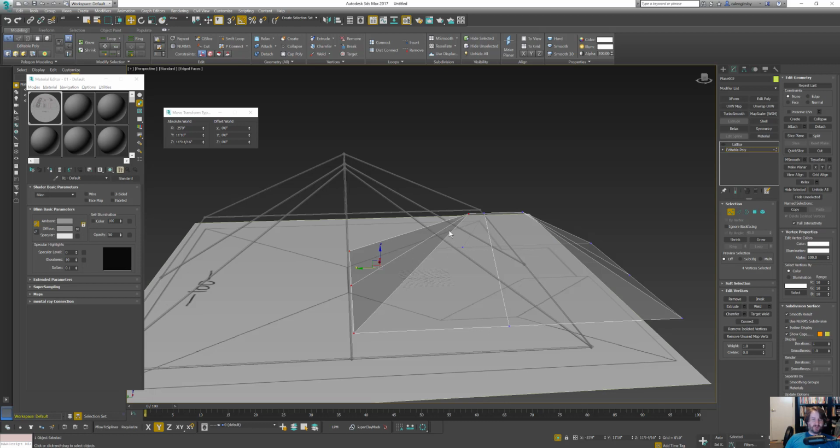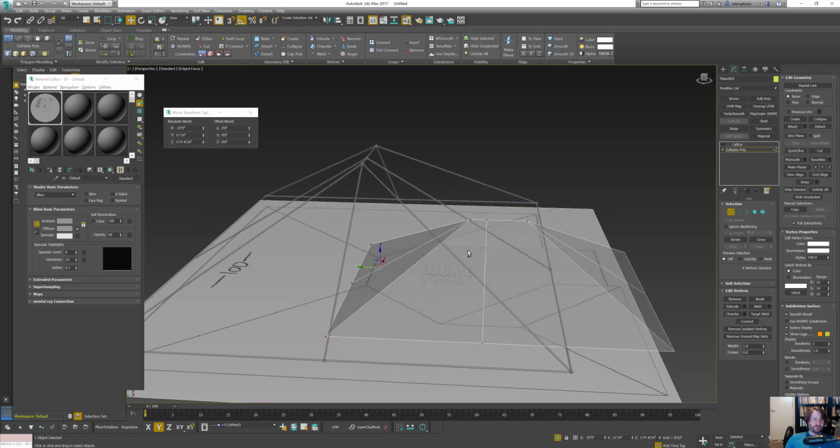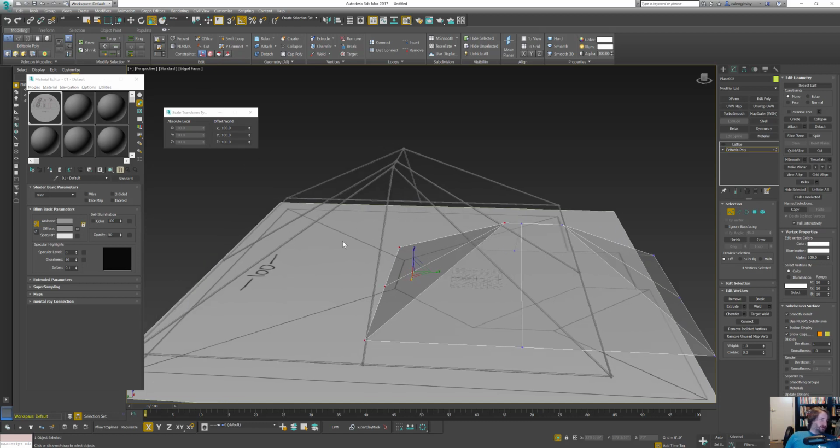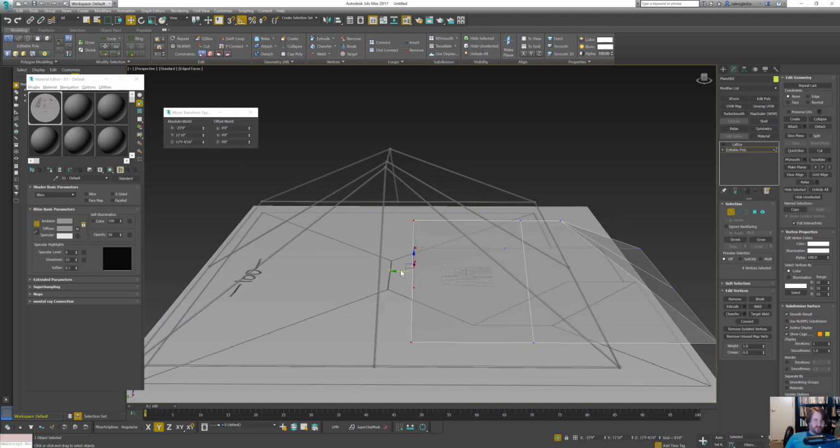Okay, I'm going to take these. I want this surface to be flat. So one way you can do that is highlight them. You can use polygons or vertex mode. I'll use vertex. You can see it's on the Y, and if you just right click the Y, oh, what the frack. Here we go. We'll do it with scale then. On the Y, right click, now it's flat. Okay, perfect, perfect, perfect.